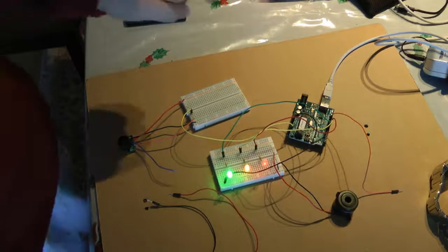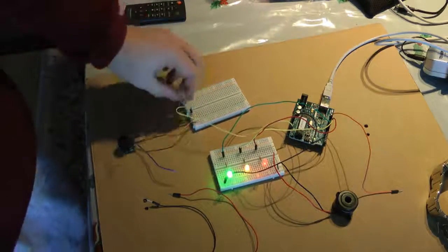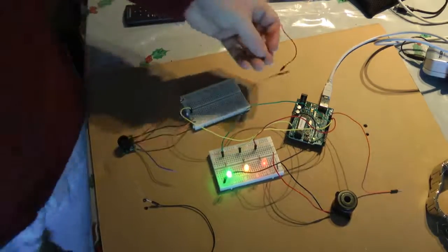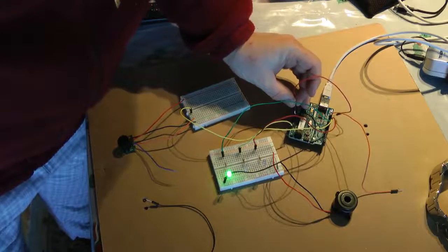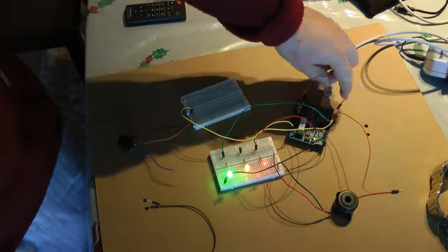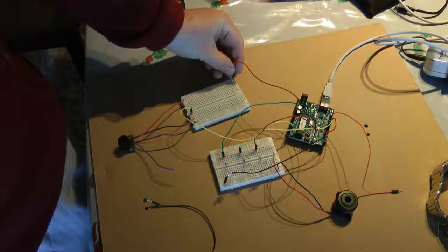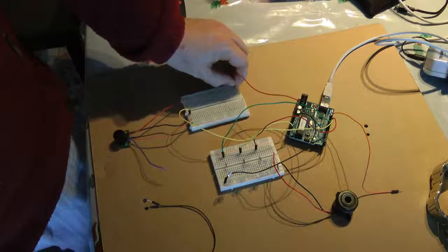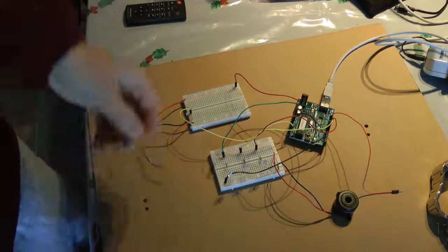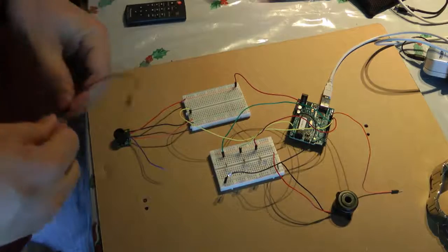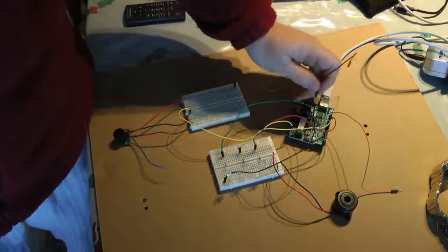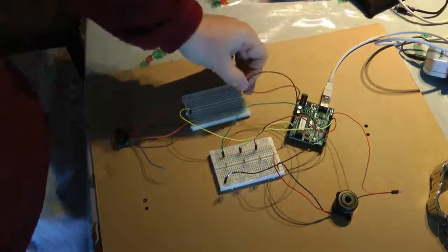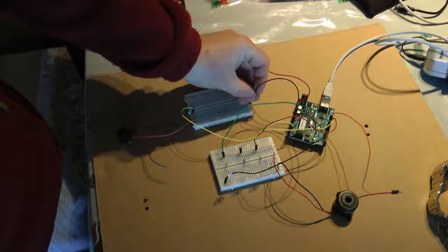Remember, we have 6 analog pins, 0 through 5. The next thing I'm going to do is take this red wire and put it in the 5 volt pin, and then bring it over to our positive rail. And we'll do a close-up of this when we're done, so you guys can get everything in case you're not getting it now. And I'm going to take the ground, and we have 2 grounds over here. I'm going to put it in the second ground, and I bring that ground over to the negative rail.